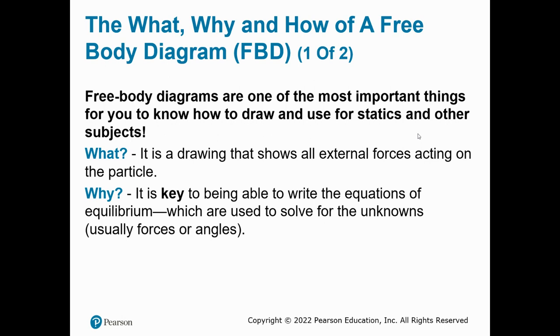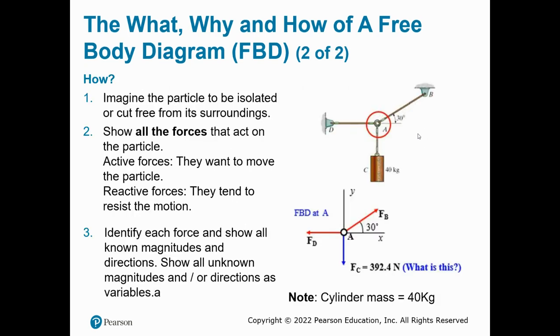Free body diagram is one of the most important tools that we're going to learn, and we have been practicing a lot of that back in physics. We will do quite some more in statics. What is it? It is a drawing that shows all the external forces acting on a particle, and it is the key to being able to write the equations of equilibrium. Without the free body diagram, we cannot write our equations. So free body diagram first, and then we write our equations. With the equations, we can solve for our unknowns.